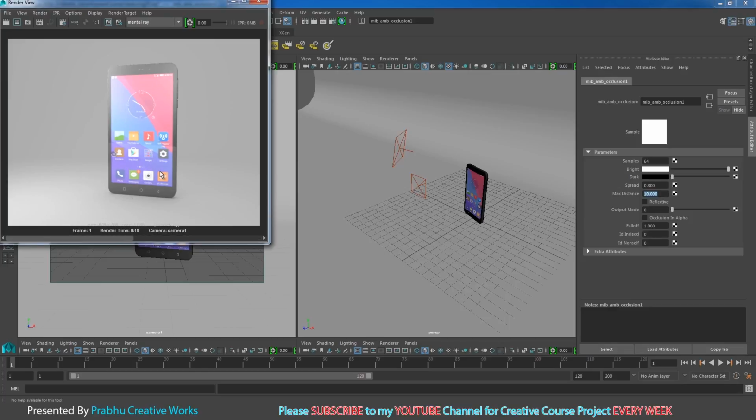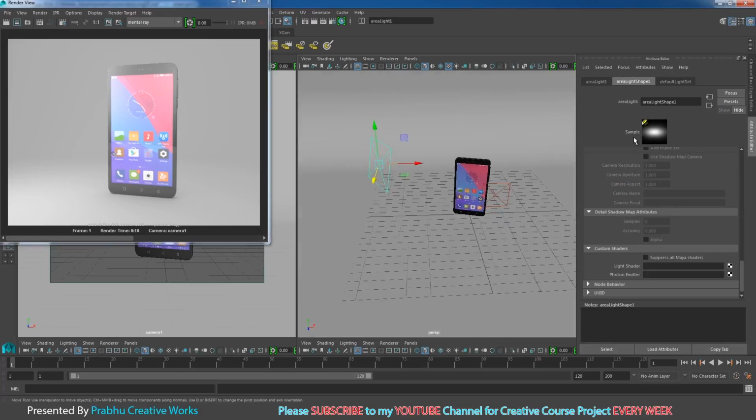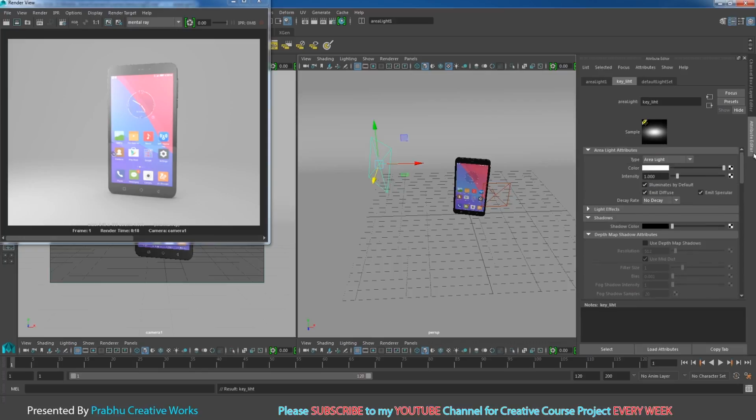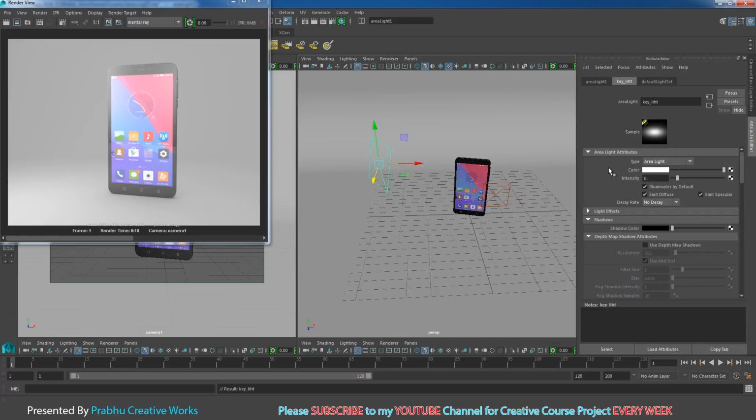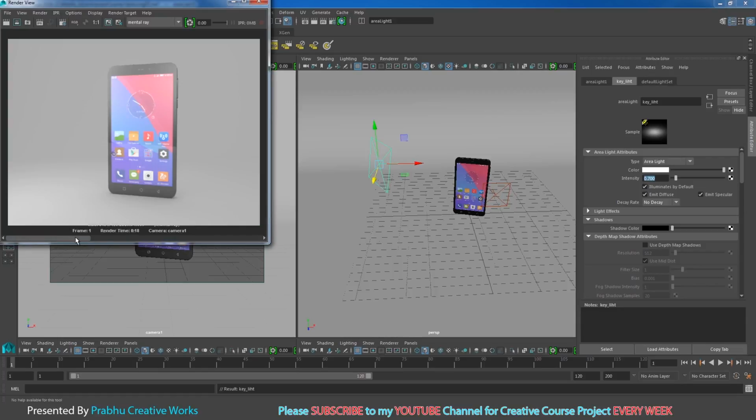Now I want to decrease the specular color for this object. So I will select my area light 1. I will rename this light as key_light. So this is a key light. I want to reduce my intensity to 0.7 or so. I will keep this image for comparison and click render. See here, I have reduced my brightness.